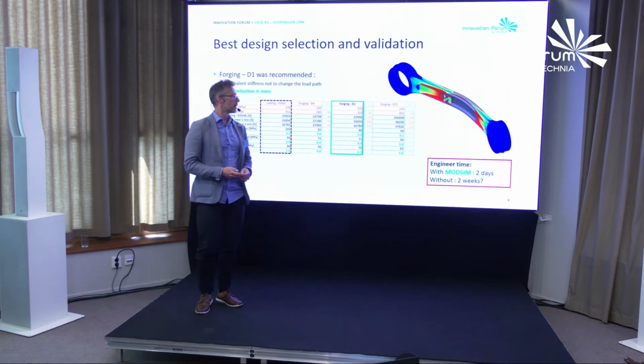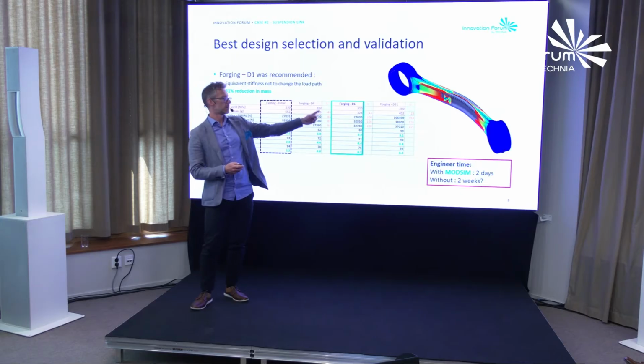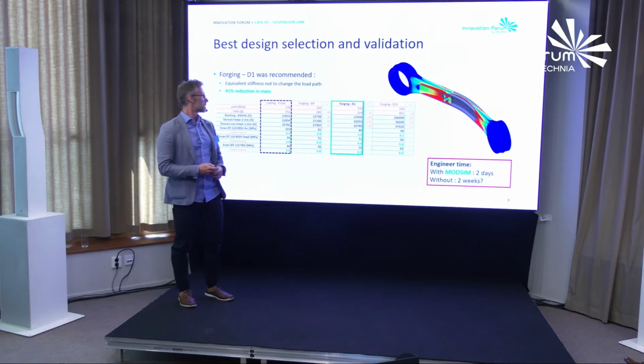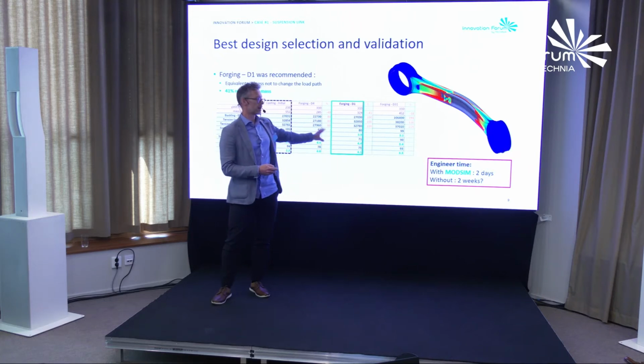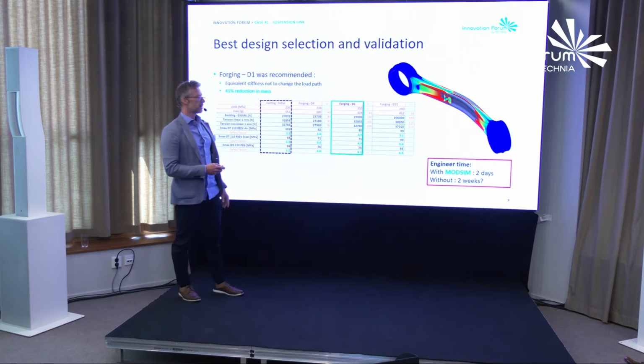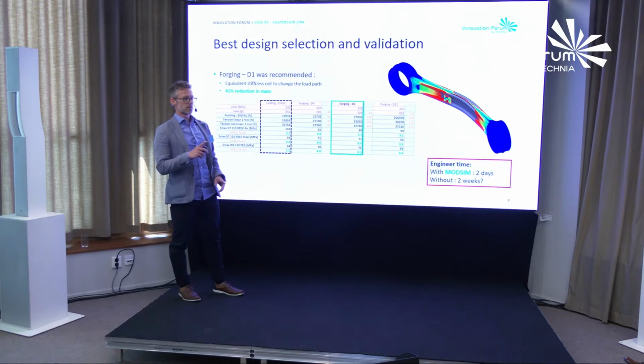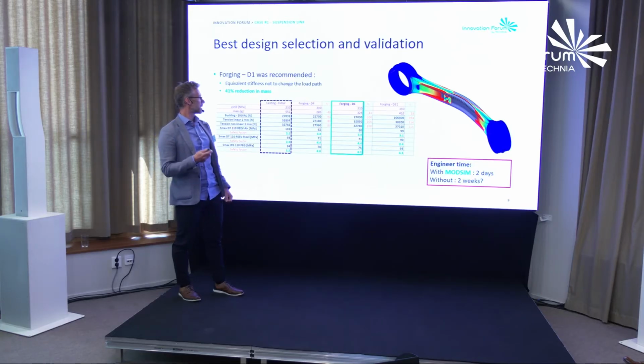This is where we ended up, this design. As you can see, this is the initial design, this is the new design: steel, aluminium. The new one matches the physical properties exactly. It has the same stiffness, same eigenvalue buckling modes, but it's 41% lighter than the old one. So it's lighter, it's cheaper, and it also matches the old physical properties.